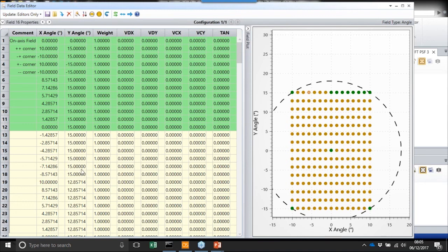One question came in about how to best set the spatial frequency in contrast optimization with regards to the merit function. This totally depends on the application. The benefit of using a contrast optimization function is that an MTF optimization only addresses a single spatial frequency. What the contrast optimization does is make it very good to trade off the contrast. If you want to optimize a contrast up to say 30 cycles per millimeter, you can take a good contrast at 50 and push it into a good contrast at 30. So it's a really nice trade-off, and it makes a much more optimized system than if you just address the MTF itself. But which MTF or contrast frequency you choose depends on the system itself.